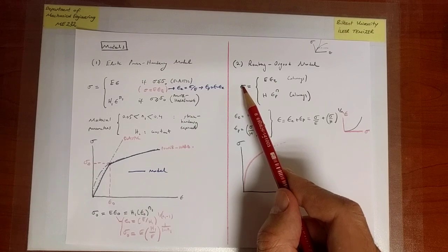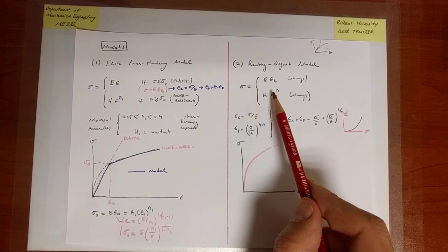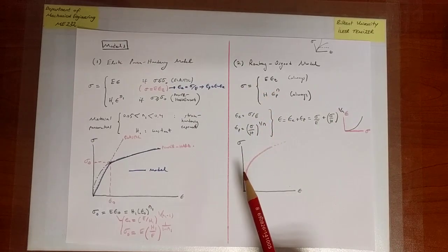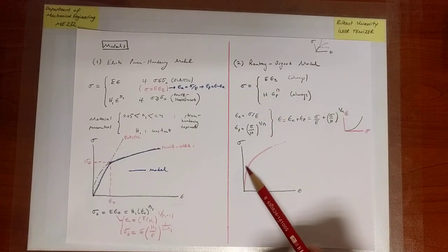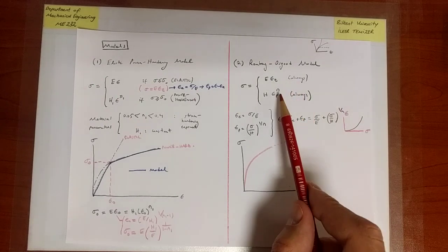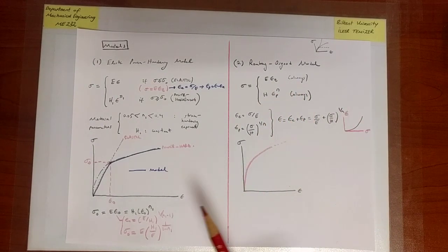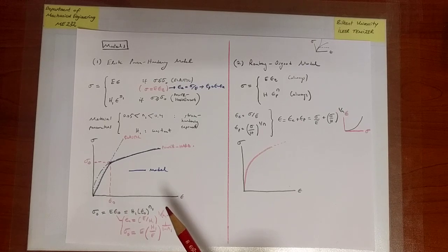So you give me a very tiny amount of stress, there will be a certain amount of plasticity according to this relation between stress and the plastic strain. And that proposal causes this elbow, let me say, instead of a corner, to form. So the Ramberg-Osgood model proposes that there is plasticity from the outset and that replicates experimentally observed behavior.